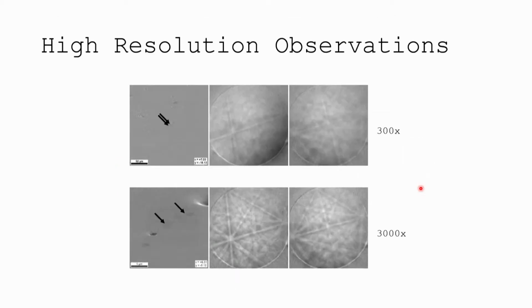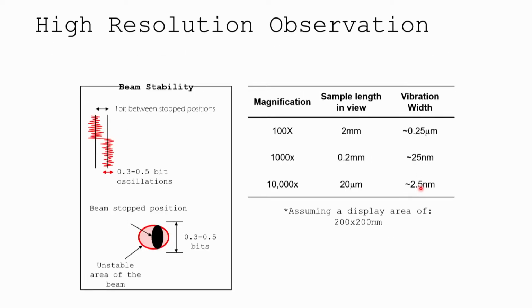Magnification in SEM, we can talk about only when we are scanning. We scan the area, then only can we talk about the magnification. Okay, there's another question, and I'm repeating it for the online people because they don't hear your questions, of course. The question is that magnification only affects the SEM when you're scanning and actually obtaining an image, because you're scanning over different regions. So if I say go to 100x, it's going to scan over a bigger region than if I say go to 10,000x and it scans over a smaller region.